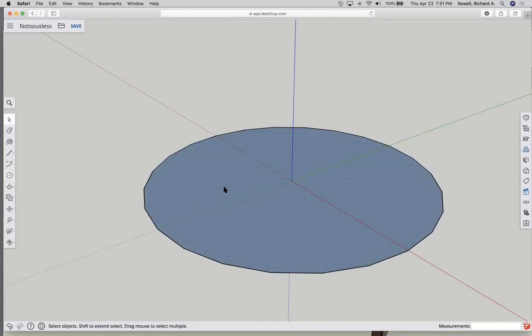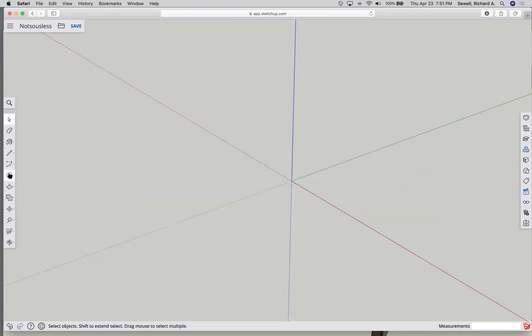Now, as I go over here, before I do anything to this, I want to change this to 48, for example, 48 sides. It can be slightly more accurate, okay? But at the end of the day, SketchUp is limited in terms of curves. You are always going to have straight lines, not perfect Bezier curves. And that is its limitation. So if you're 3D printing something and you want it to be perfectly round, perfectly curved, or if you have complex shapes in there, that's where SketchUp has a tendency to start to falter.